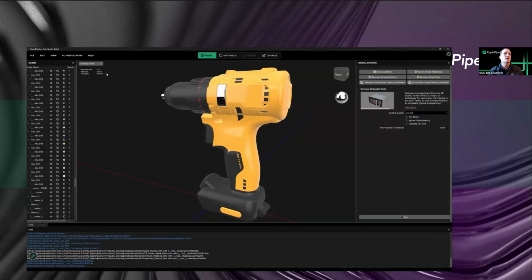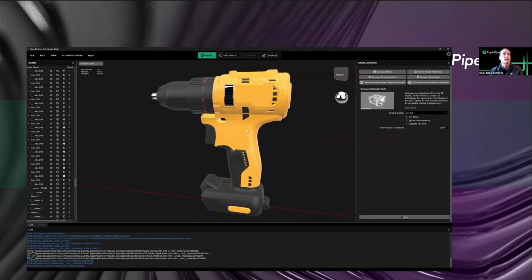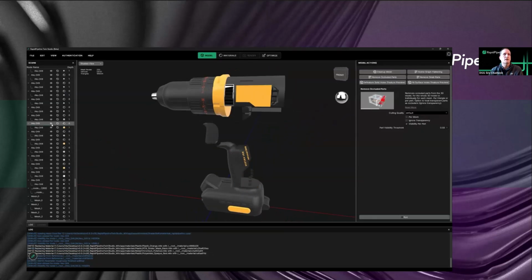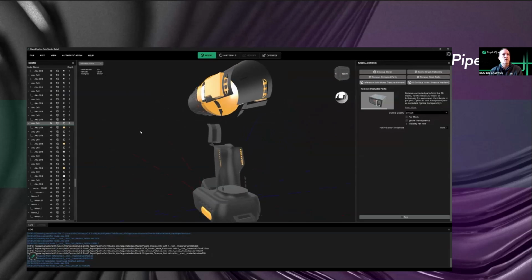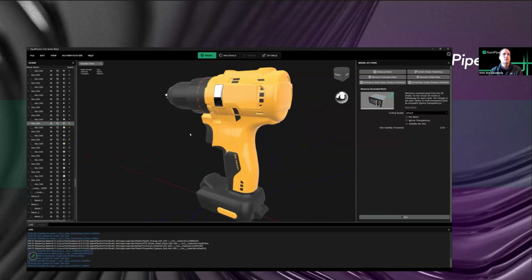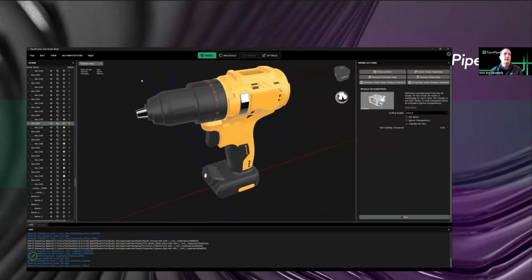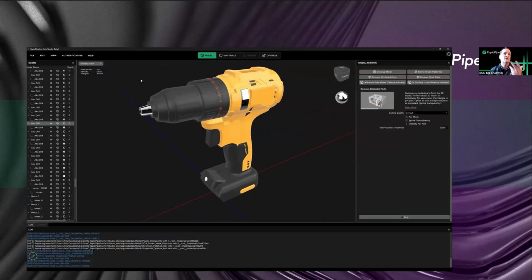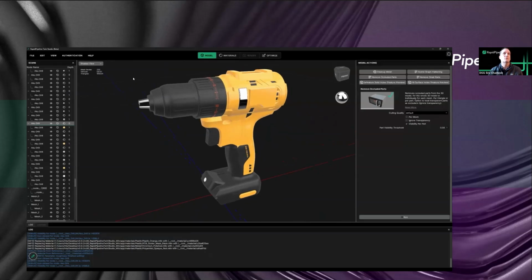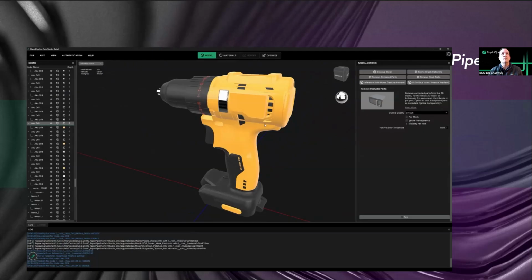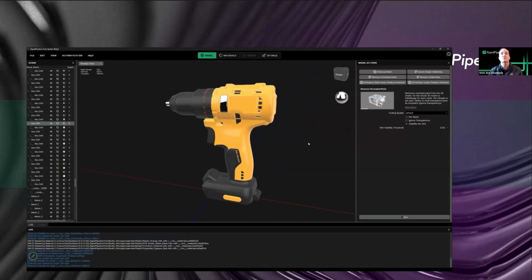And one thing that you often get with CAD assets is it's got a ton of nodes, right? It's got all those parts inside. I think we did do the occlusion culling, so we removed all those screws. But even after removing the screws and those interior parts, we still have 220 nodes, and that's going to increase the render cost of this asset. It's also got 106,000 triangles. So we can definitely get that down to a lower number and less nodes.